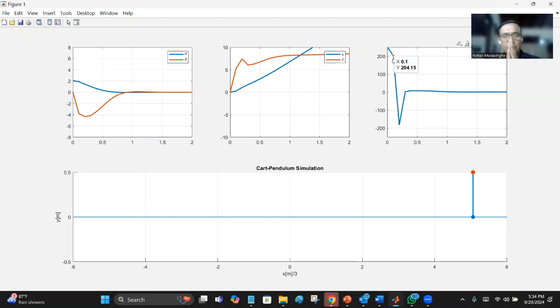Again, what we have to understand is that there's no such thing as one size fits all. If you want to handle a complicated problem with a wide dynamic range, you don't have a single controller that is able to handle all these things, right? You need to switch from one controller to another, depending on your operating point. That is the final learning over here.